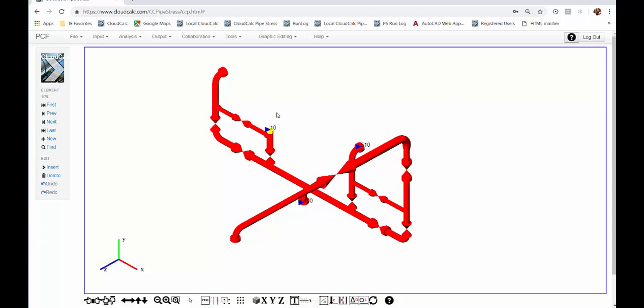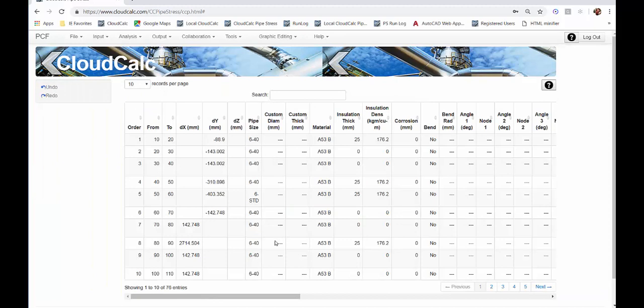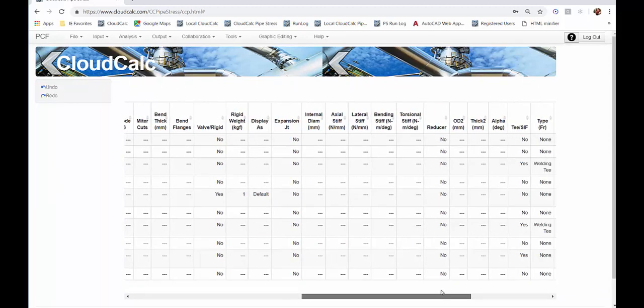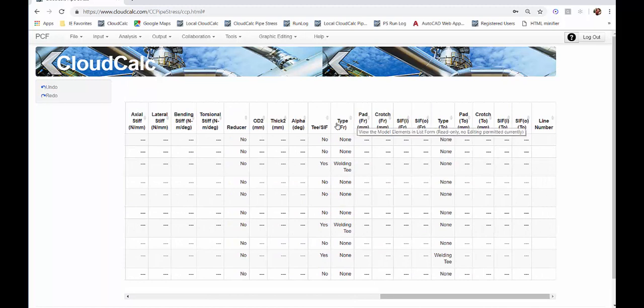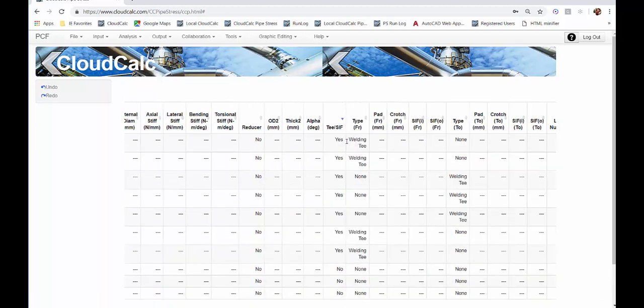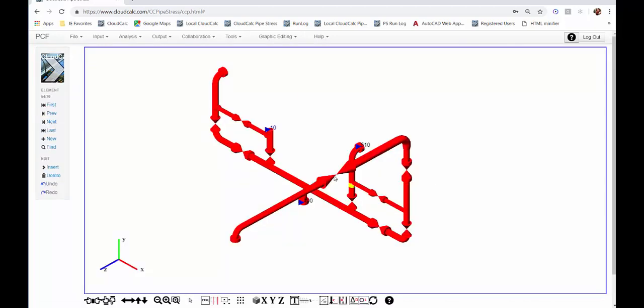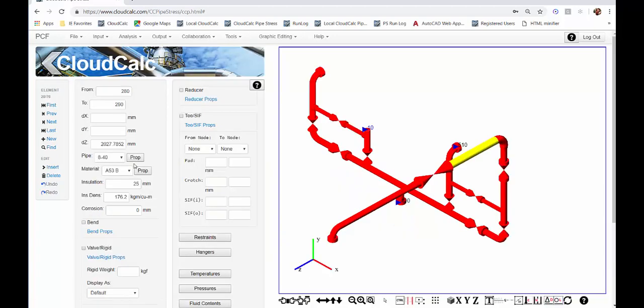as mentioned, most of the geometry comes in, the types of bridges, flanges, etc. The T's, if we look at the T's, go to the list view. Okay, welding T's, etc. came in. So the different stress intensification factors, the different component types, the wall thicknesses and schedules. We look at this. So 8-inch schedule 40. Everything comes in.